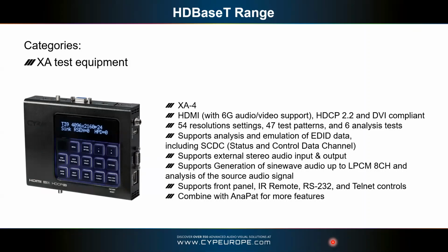So if you want to put an input into this, you can then measure things like the EDID. You can export that using systems like Anapat, which is sort of a PC-based software. So again, more of a sort of engineer's tool. This has VGA as well as HDMI. So again, it's a little bit more advanced than the portable, but again, just a really good option for testing products.